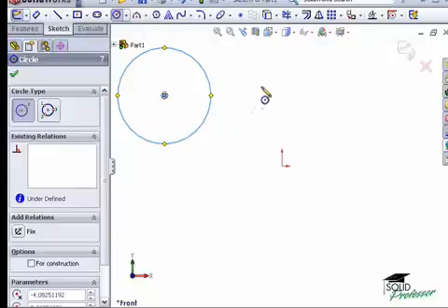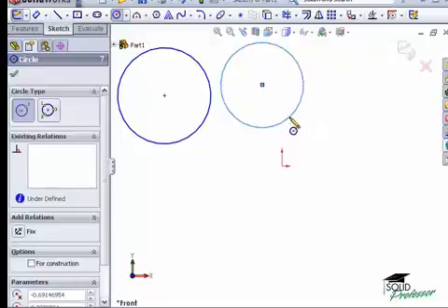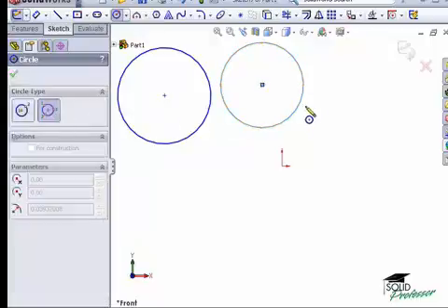The click-drag method works as well. Click to define the center, hold down the mouse button, and release it to define the radius. Next, I will switch to the perimeter circle. As you can see from the icon, I need 3 clicks each representing a placement of the outside of the circle.